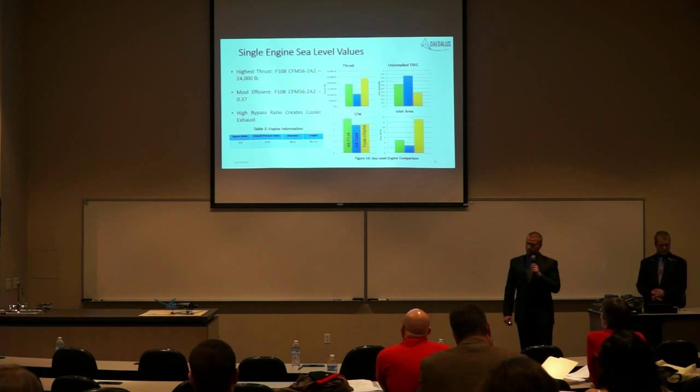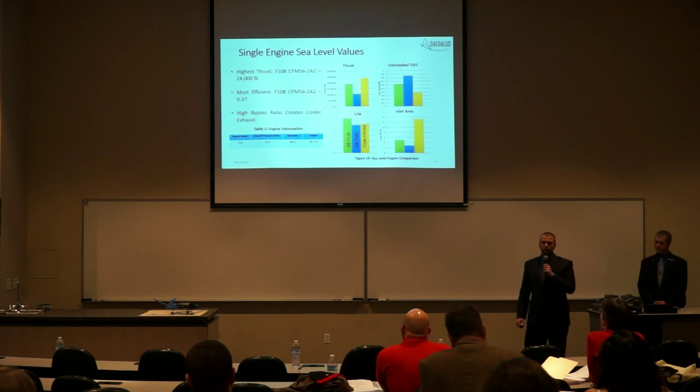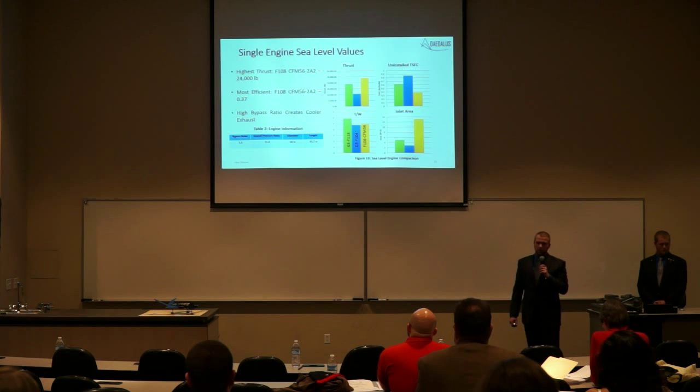This higher bypass ratio, however, of 5.9, is an advantageous quality in terms of LO. Due to the higher amount of free stream air that passes through the engine, our thermal signature is going to be reduced a lot.